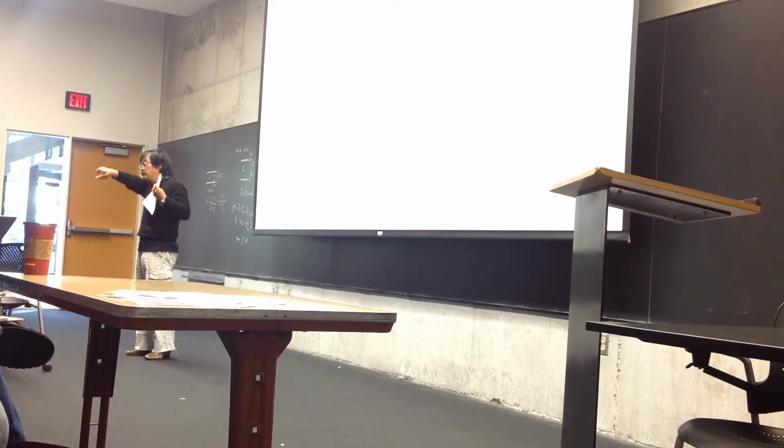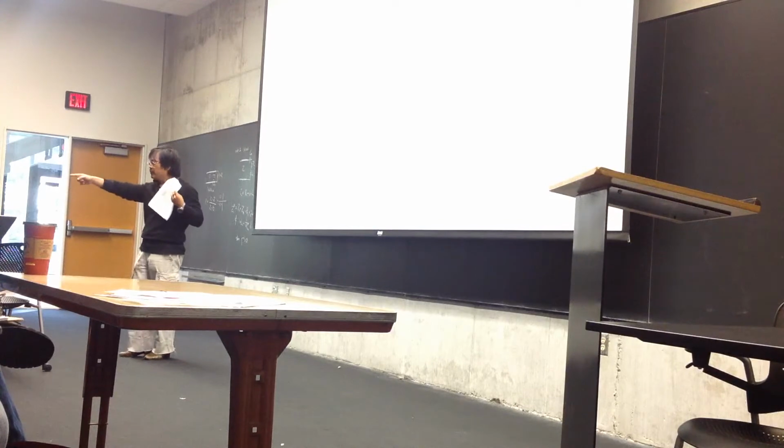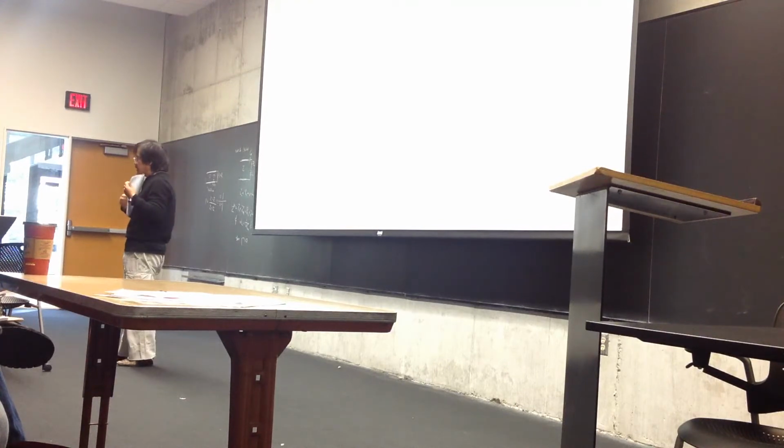Again, use the compass. You can use it to do that. Constant radius circle. So you go from this point on the circle to the opposite point on the circle. Okay? And then to answer your question, you have this constant radius circle now, and that constant radius circle is going to intersect with the R equal to 1 circle. And that's the point. The intersect is the point that you want to do the matching, because that point will have the real part of admittance equal to 1. And there's going to be 2 points, right? And you want the one that's the opposite sign.